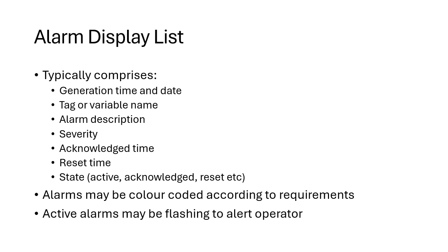So green is normally normal, or maybe blue, they're sort of cooler colours to indicate that not too much is required. Green is often associated with normal. Orange would be a warning, and red would be an actual alarm state. But some people have different colours. Sometimes red means that something might be in a normal state, and green means that it's actually active. So a bit like traffic lights. Red is stop and you don't do anything. Green is go and you need to take action. But in my view, that's rarer. Normally the colours are blue or green for normal, orange for warning, and red to take action.